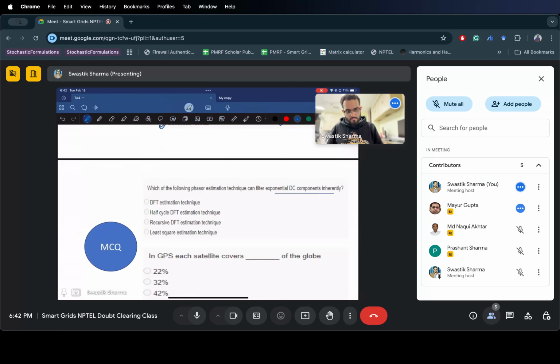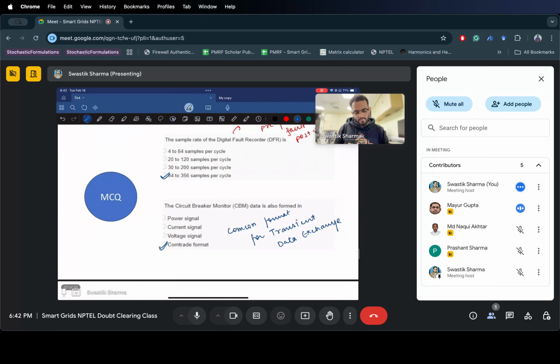This is done because there are multiple vendor relays, say GE, Siemens, Micom, Schneider, and many others, and you want them to generate a similar file, a universal format which can be read by anyone. Otherwise, everyone would generate their own format, and it would be difficult to exchange this information. In case of any event, it is required at times to read hundreds of relays at grid scale, so it is easier to collect this data in one format and have it read by any person.